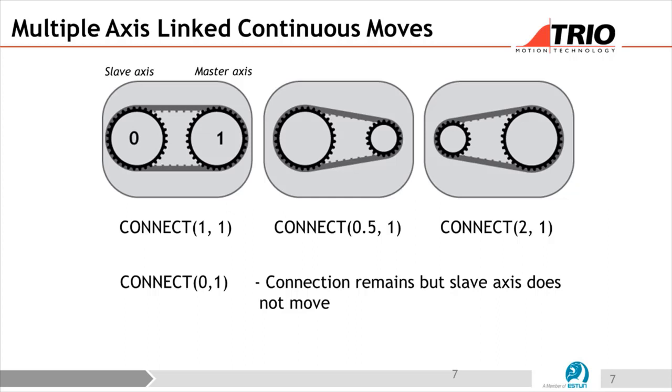Generally, in my experience, anything up to 5 you don't notice this effect at all. It's fine. When you get to 10 you might see a bit of nervousness in the axis. Above 10 and really you're into a territory where it's not going to perform very well. However, having said that, the assumption there is that the master and slave axes have the same number of counts.